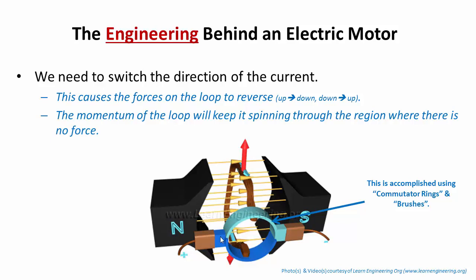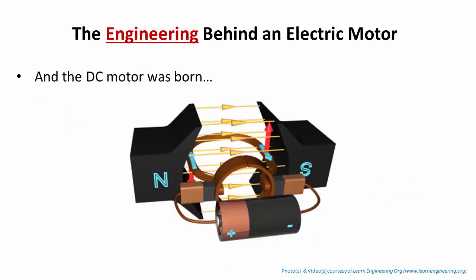So now in order to allow this ring to spin, the ring is actually connected to this coil of wires. They use these brushes right here that have springs in them, and this provides basically a mechanical connection. It's a spring that pushes these brushes down here, and it allows this thing to spin and make electrical contact. So that's how the DC motor was born.